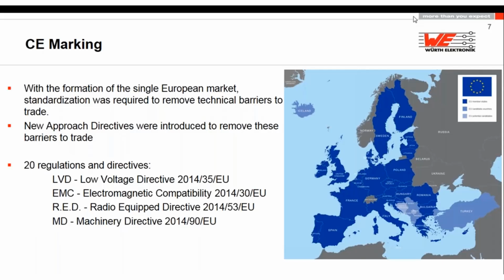The Machinery Directive for industrial machines also includes the EMC requirement. So we have different directives, which right now are only valid under the 2014 law. If you still use the law from 2004 or 2008, they are no longer valid. Please consult your EMC lab when you're doing a declaration, otherwise you're not compliant.